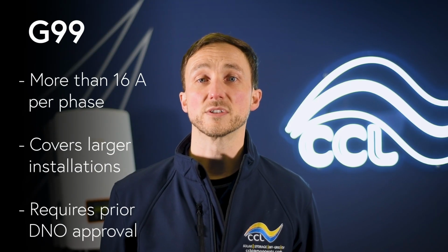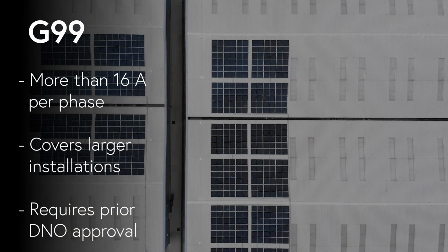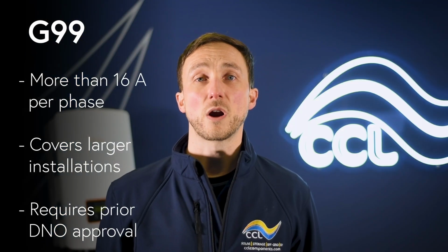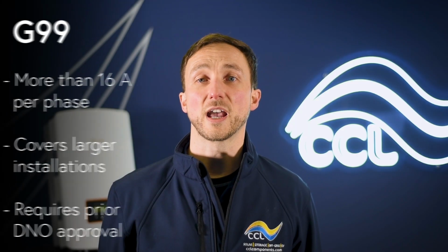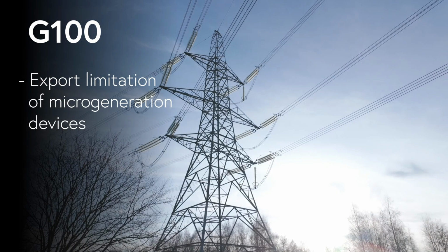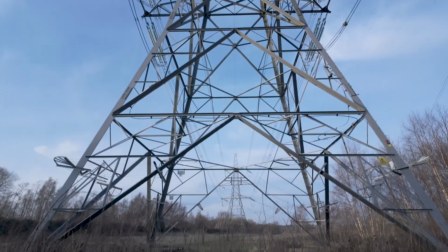G99, on the other hand, covers larger installations beyond the G98 limits, including commercial and industrial systems. These require prior DNO approval, since they can impact local grid stability. Then there's G100, which deals with the equipment that limits the amount of power exported to the grid due to DNO restrictions. G100 can apply to the generation equipment itself or to additional devices such as meters that can ensure compliance for entire systems.